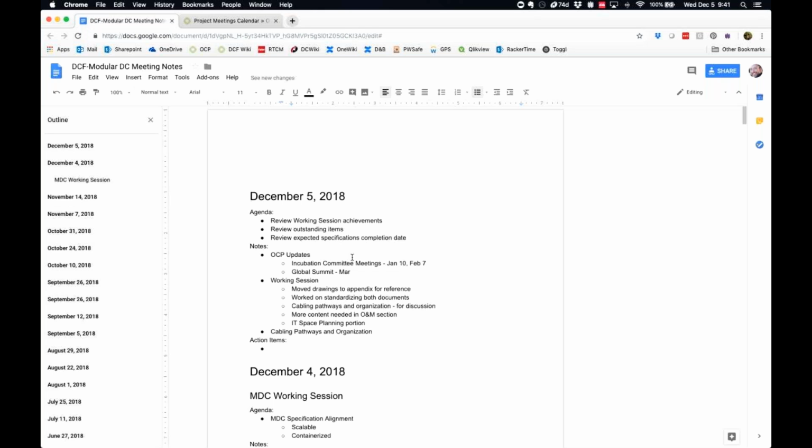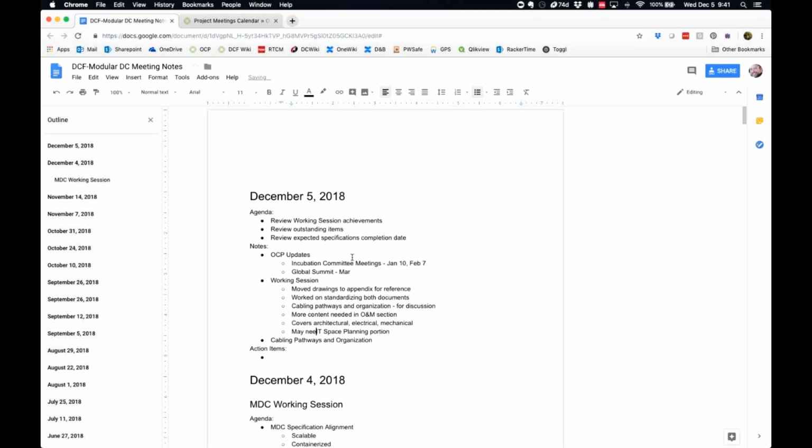I think this is important information. You have 1200 between the rows, so you can move racks in and out and also perform maintenance. You have enough space behind in the double row with 650 millimeters. And some comments should be in there, saying it is good enough for the purpose we have. We have had some discussions about the communication racks that you need to connect from the rear side. Wasn't that so? Brevin, help us out here.